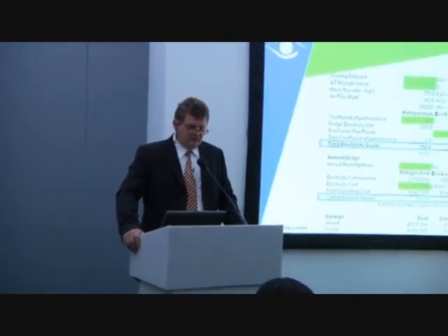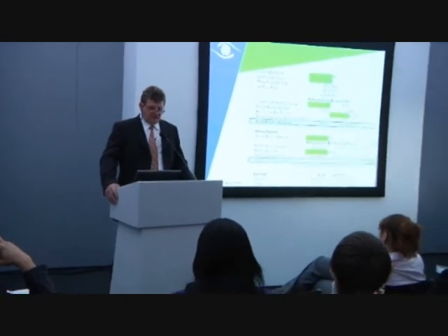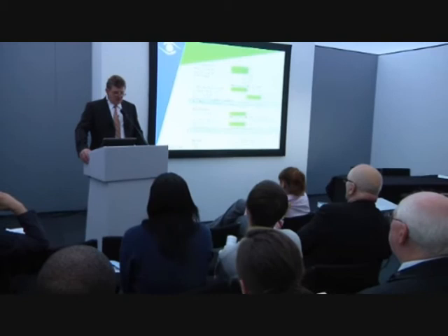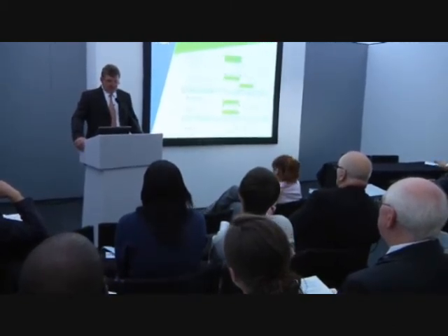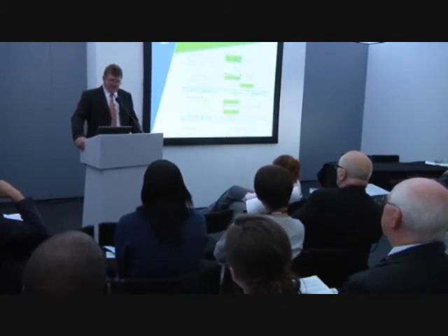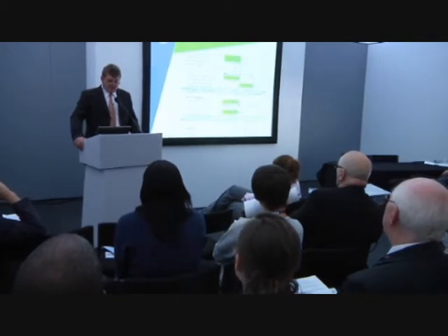There's a little bit more to it than that. What we're actually trying to do is give all the servers the right volume of air. Wherever that air comes from is irrelevant, but you've got to give it the right volume. Now, 500 kilowatts of servers actually adds up to about 42 cubic meters per second of air. That's a lot of air. Where does it come from?